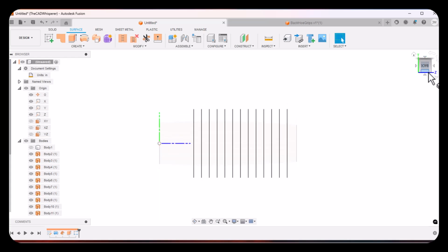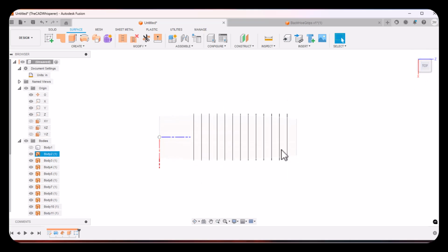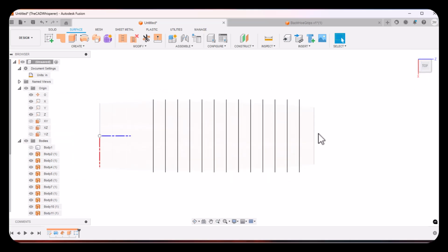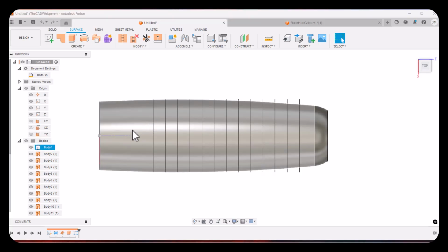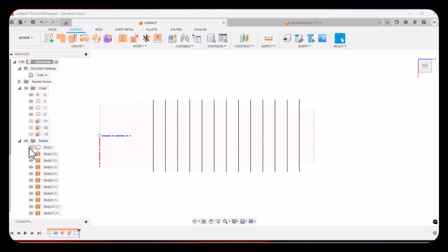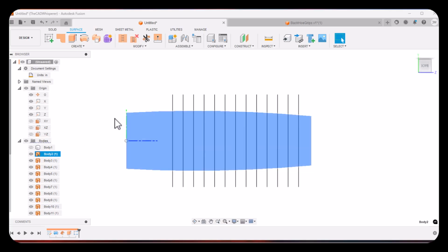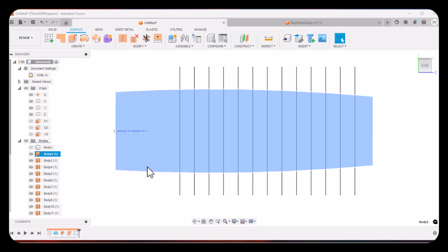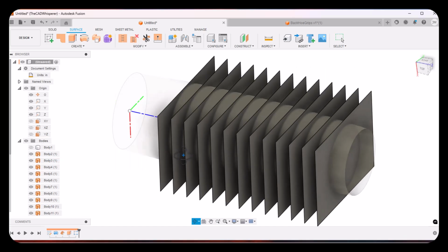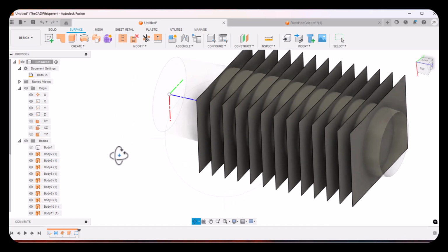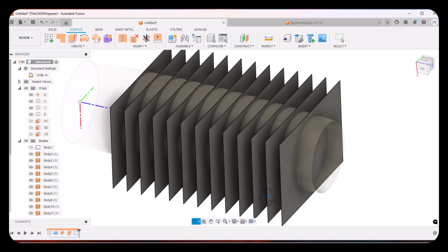I'm going to go around to the top view. Now it might not be real apparent here, but because I turned the transparency or made that the offset surfaces, remember the offset surface is inside the solid body. I want to make sure that I get just these extruded surfaces, and so I don't want to get this surface right here when I do my trimming. And so to do my trimming, then I need to trim a circle in each one of these surfaces.